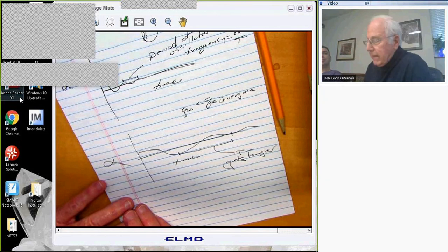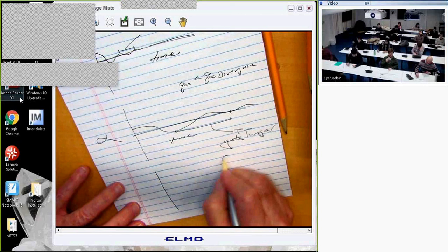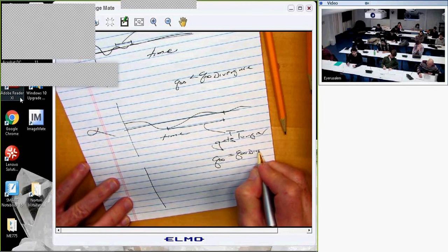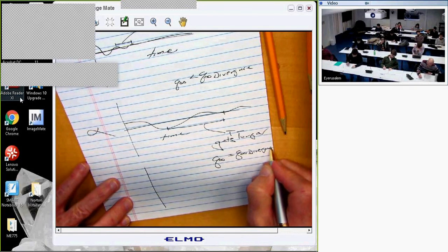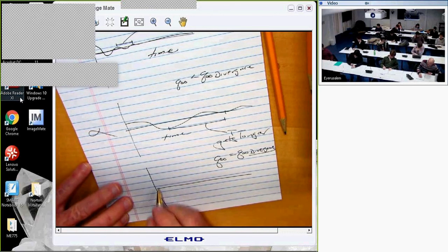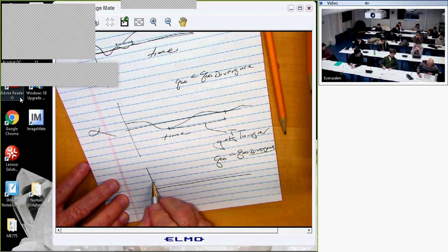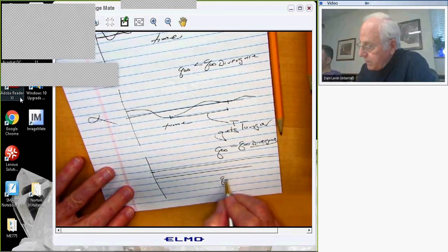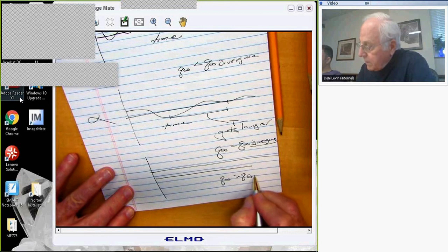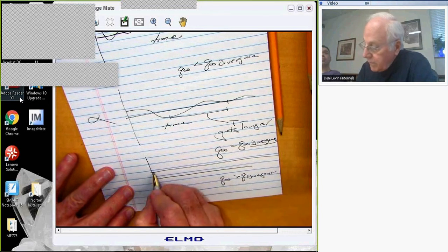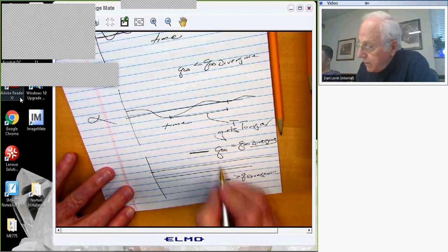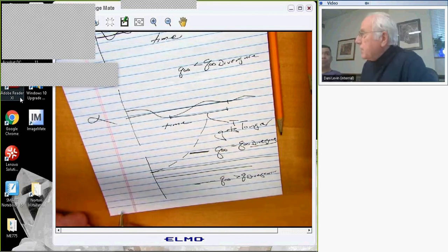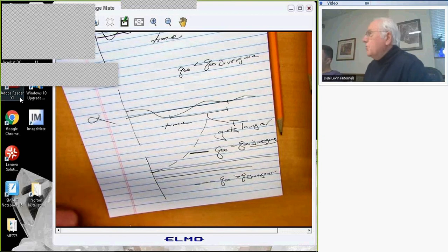And then if I'm right at divergence, and I start here, it doesn't decay at all. And if I'm above divergence, I'm going to make that a solid line. I'll make this a dashed line. If I'm above divergence, it actually grows exponentially with time. There's no frequency. The frequency is zero once I'm in the divergence.